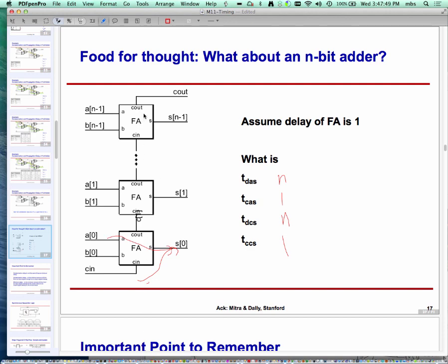So that depends how you define TDAS. If I keep all the lower bits constant and I change the MSB of A, then the TDAS will be different. But again, I have to be prepared for all possible values, right? So A is a multi-bit signal, S is a multi-bit signal. Across all possible pairs and all possible scenarios, I have to make sure that it's true. So the worst case would be one where the carry propagates through all the bits.